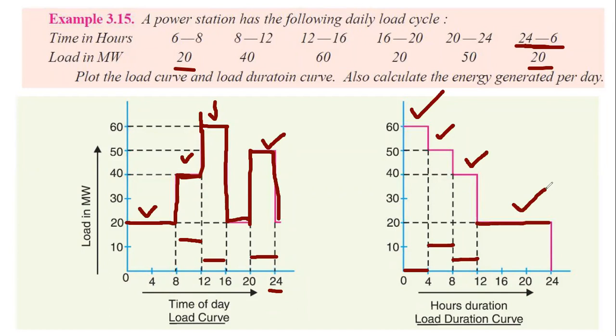So what is the advantage? The advantage is that from this load duration curve, you can easily tell how many hours a particular load amount is going on.